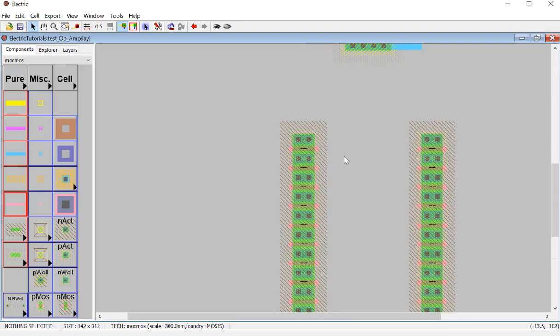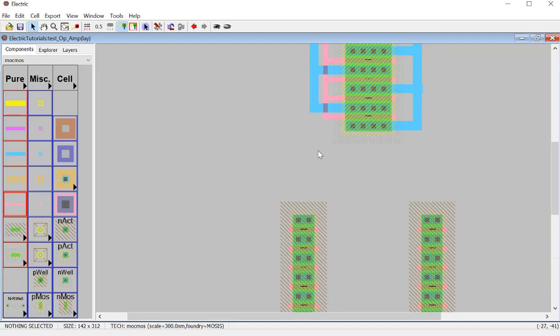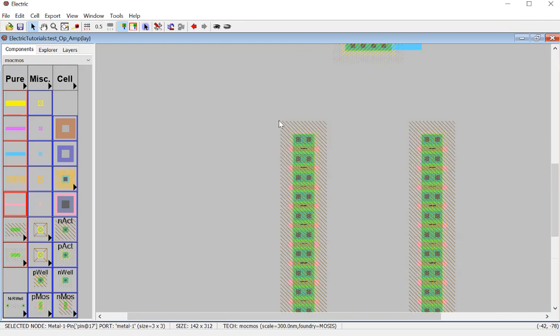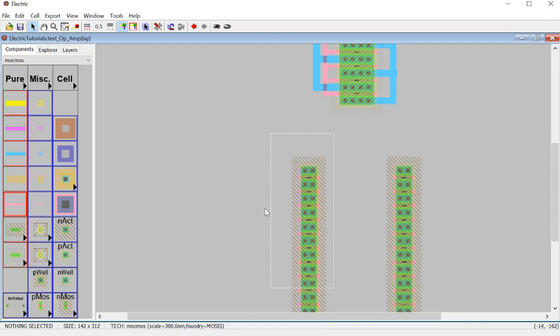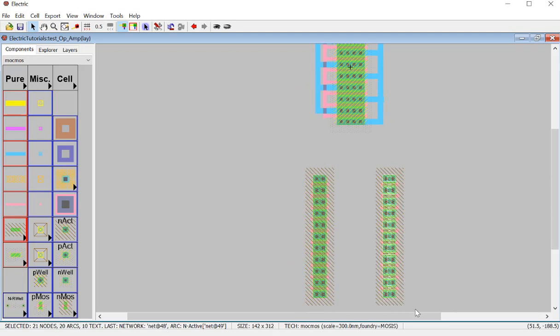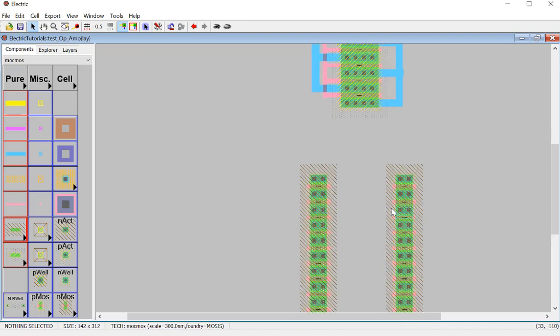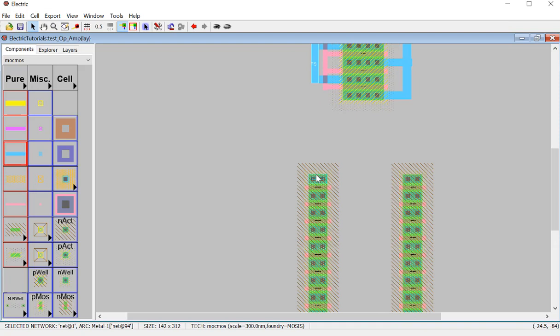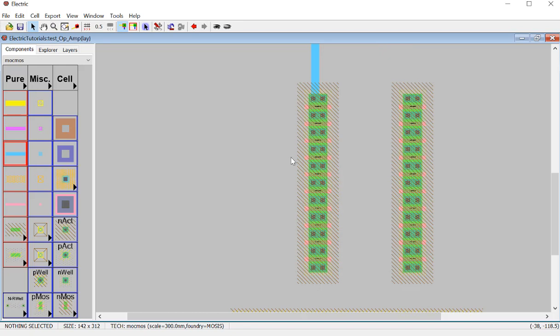So that's source, that's the drain. Let's do F5 very quick, so no errors. So source, drain, and the drain is being connected to the drain of the first NMOS, right? So now let's draw it. I'll probably move this one closer so I can directly connect it to the drain of this NMOS, and the same to here. It's not hurting to move it a little bit closer, and here to this node. All right, and it's the same concept, right?